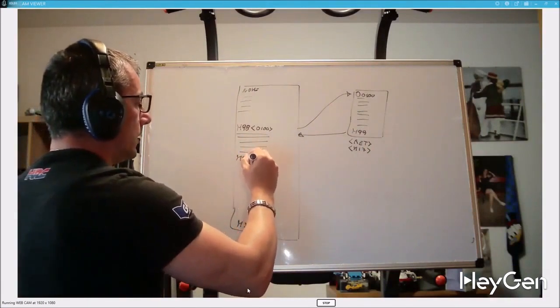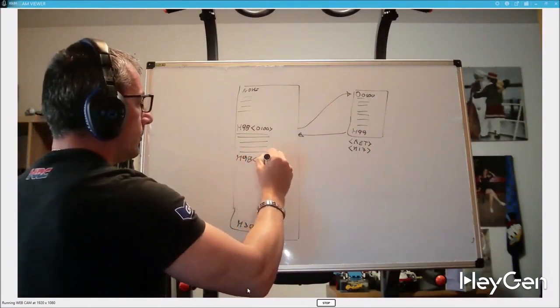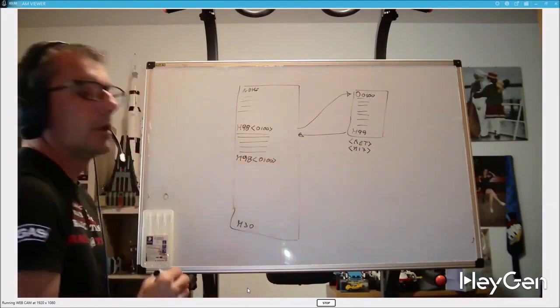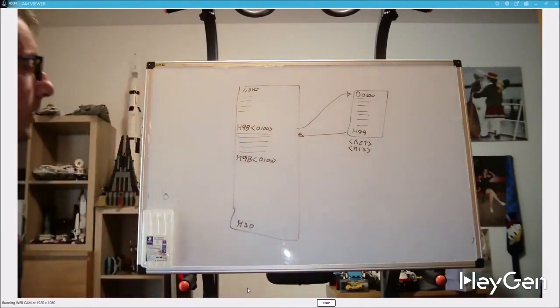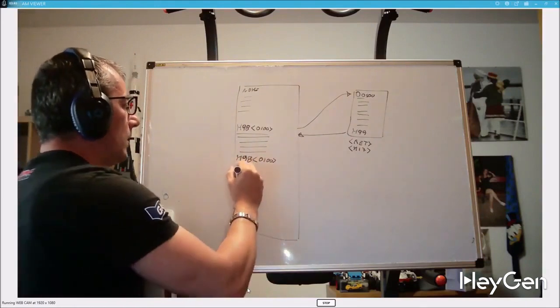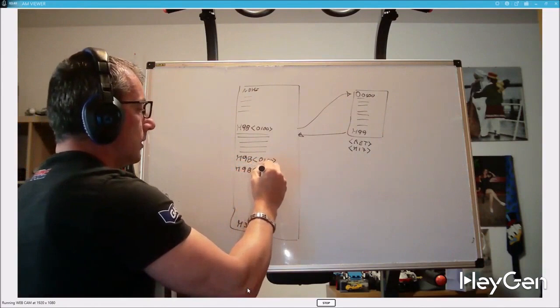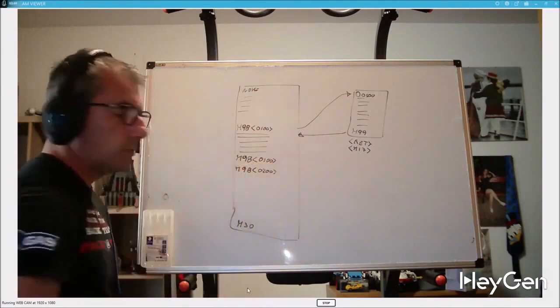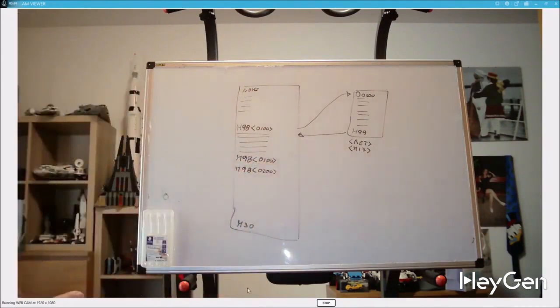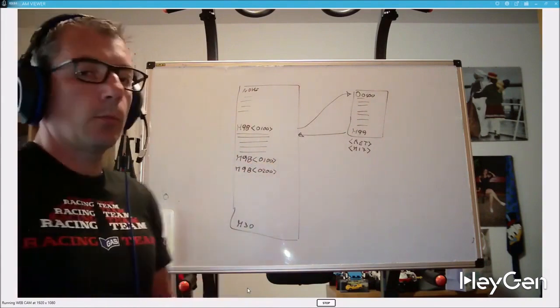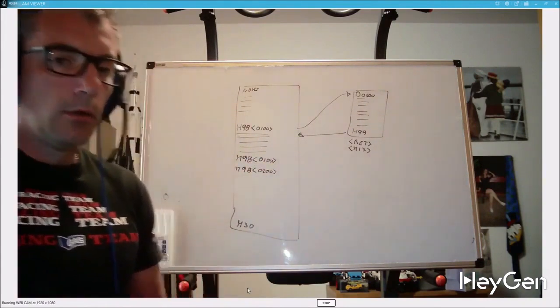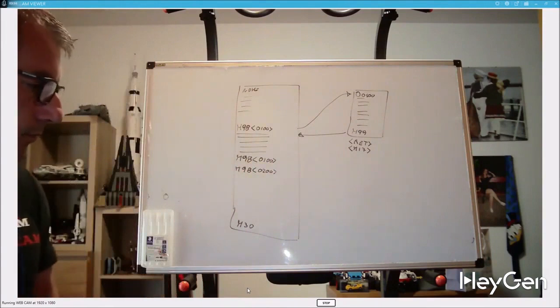For example, we might have parts that are all the same in diameter and length, but the section changes. I'll perform the chamfering and external turning in the main program, then create a series of subprograms to handle this hollowing out, done differently each time. With the drawing, I'll call programs 0100, 0200, 0300 within the subprogram. For example, imagine we have a bar and we need to make a 4mm groove.